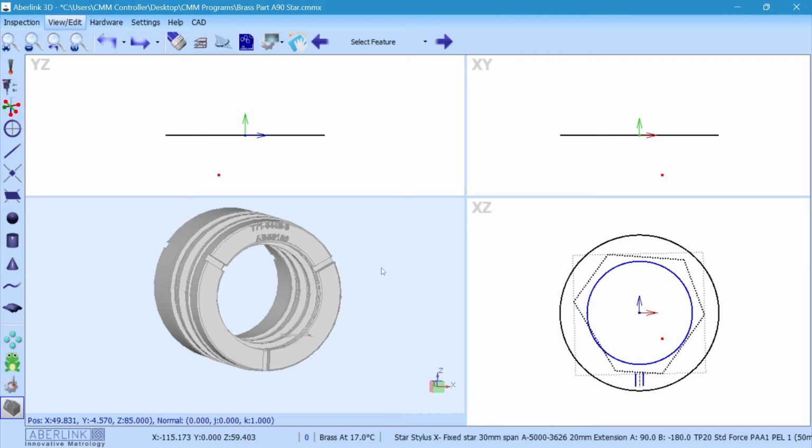As mentioned, the key thing here is that we need to make sure the Z- offset on the star probe is active before we open the feature. That will predetermine the correct vector, in this example going through the front of the job and exiting through the front of the job, but the same principle applies no matter which head orientation you are using. So set the Z- star probe as active.